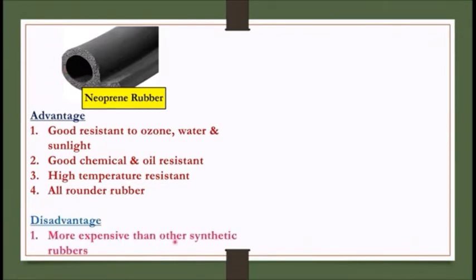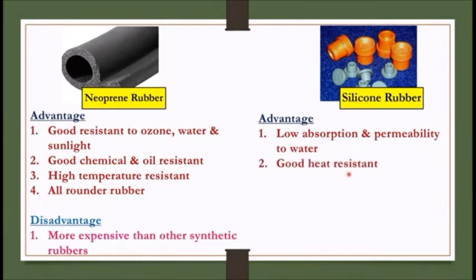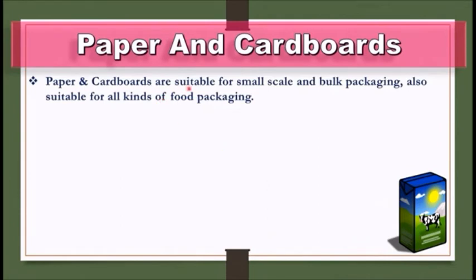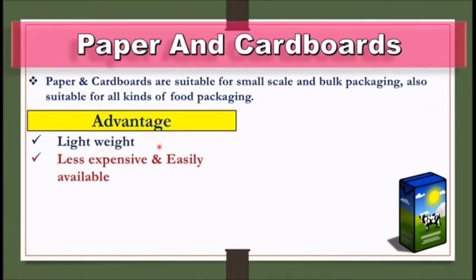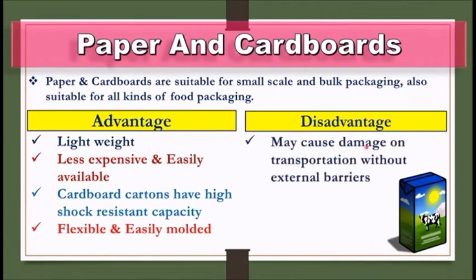The concentration of antistatic additives is normally 0.1 to 0.2% in high density polyethylene. Next one is polypropylene. This polypropylene does not stress crack under any condition except with non-aromatic and halogenated solvents, and it is suitable for boilable packages and for sterilization products. Also, polypropylene has brittleness at low temperature, and it blends with other polymers easily.